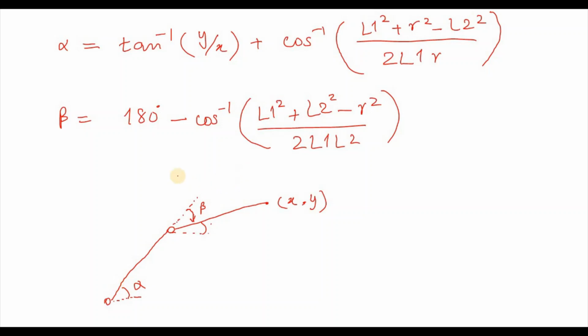So these angles will be used by your controller, the controller that controls the position of your end effector, to maintain an error-free position of your end effector. So it will give commands to these motors attached to these joints to stay on these given angles.